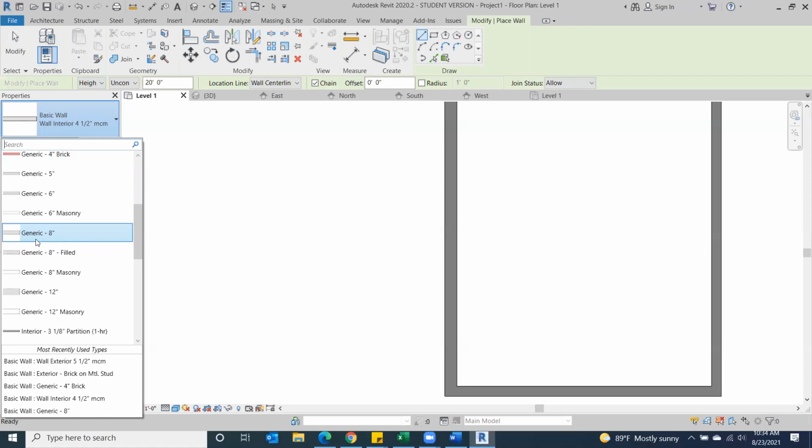That's fine. That must be where I went wrong, because now even my interior walls that I created, the 4.5-inch interior wall, even those are brick. So that must be the place where I went wrong. Yeah, it's using that one to start with. Always make sure that you use a regular generic. Use the generic, but it's a brick generic. So that's going to make them all. That will make all your walls brick, and then it just makes it harder for you to change after. So just always start with that default of the generic 8-inch wall to start with, and that'll do it.